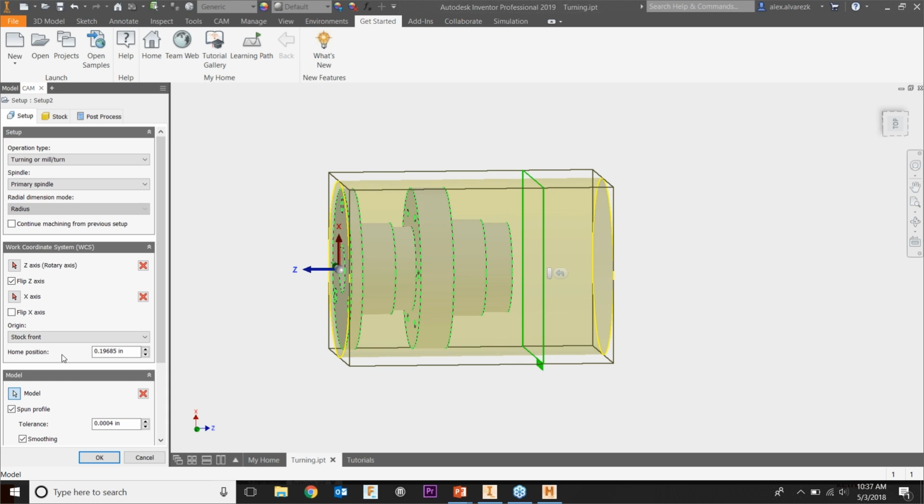Do you get full 5-axis HSM in the Product Design and Manufacturing Collection? Go ahead, Alex, and answer that question. Yeah, you do. Sorry about that, I was still pretty shocked at how the toolpath regenerated when we flipped the work coordinate system. But yes, you do get full 5-axis, simultaneous and indexing, so 3+2, 3+1 as well. Hopefully that answers some of those questions.